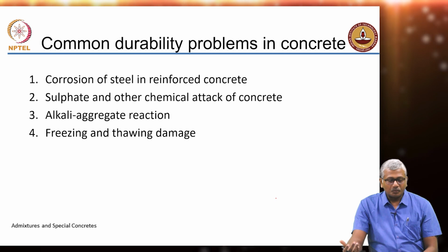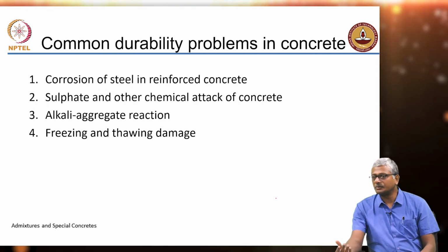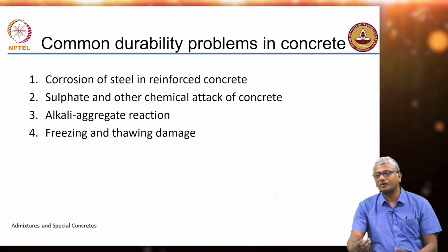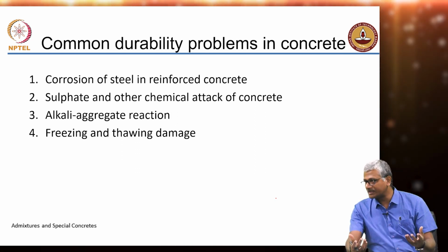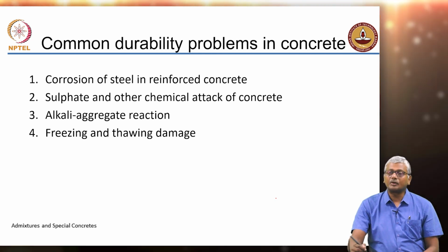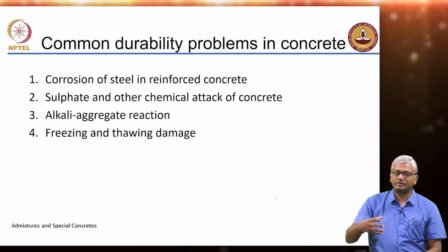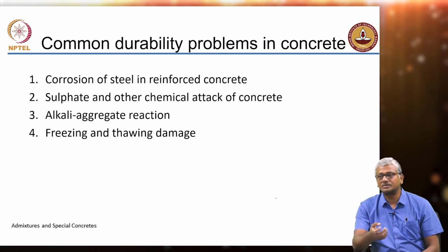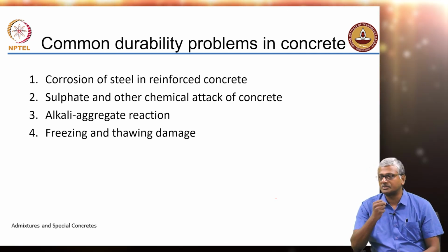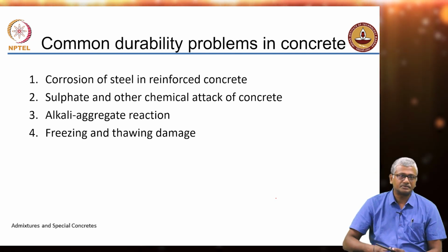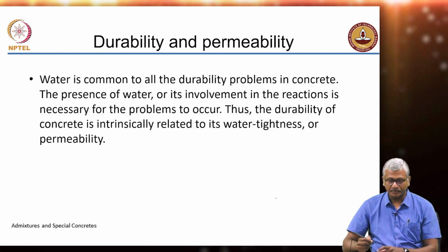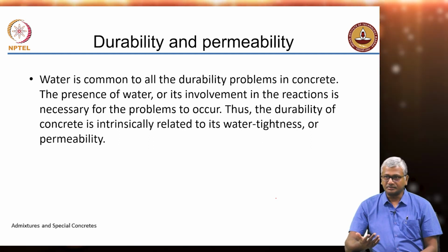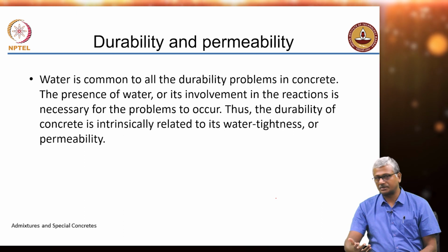No. Why? Because corrosion of steel, you need moisture for the reactions to proceed. Freezing and thawing obviously is the penetration of water, conversion to ice and so on. Chemical attack can only happen when the water penetrates the concrete with the salts that damage the concrete. Alkali aggregate reaction, the expansions happen because of the imbibition of water. So, without water, you do not really have a durability problem. So, generally water is either involved in the reaction or is necessary for the manifestation to occur.